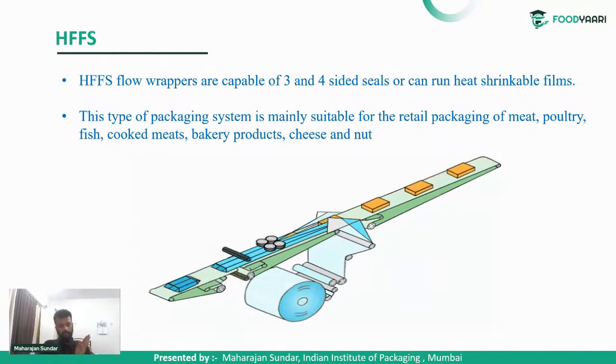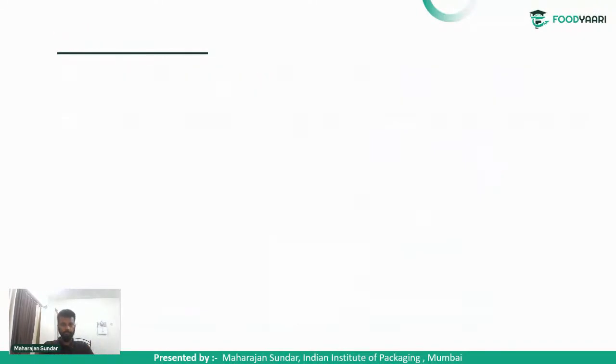While sealing the bottom of one end, it also seals the top of the other end, and also cuts it and detaches it from the line. Here it is also possible to apply vacuum, so the total air present inside can be removed before sealing.